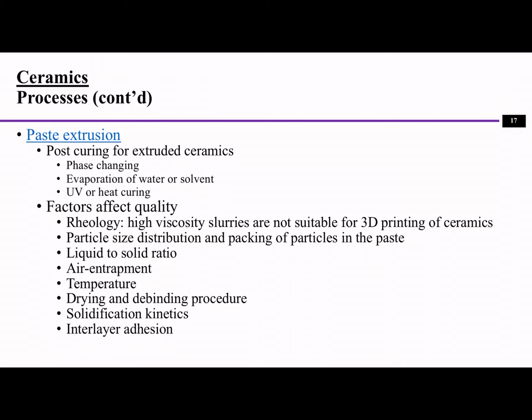Some of the factors that affect the quality of paste extrusion are the rheology factors. For example, a high viscosity slurry is not very good for deposition, and the particle size distribution also matters, because particles are combined with a liquid to make the paste.